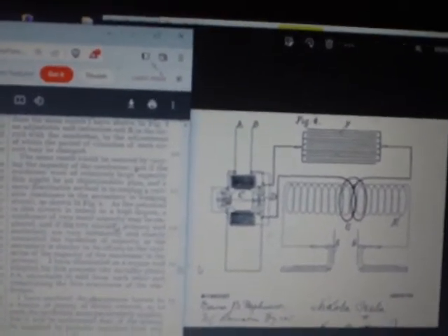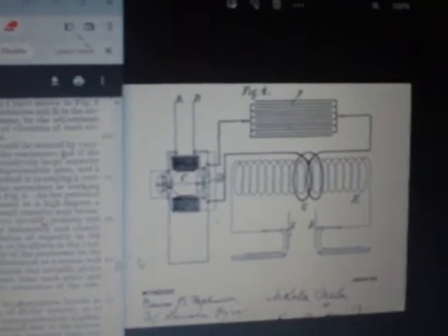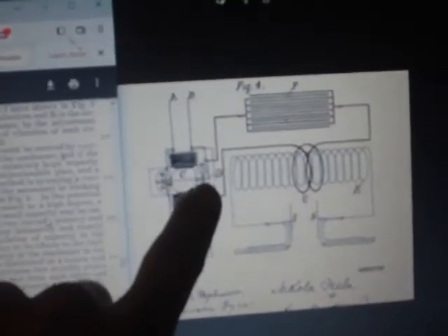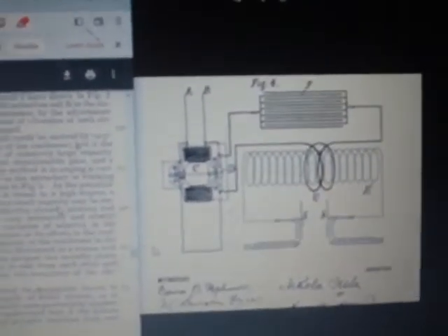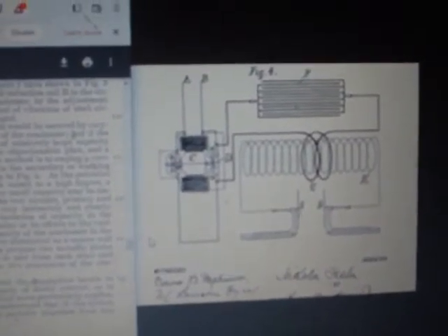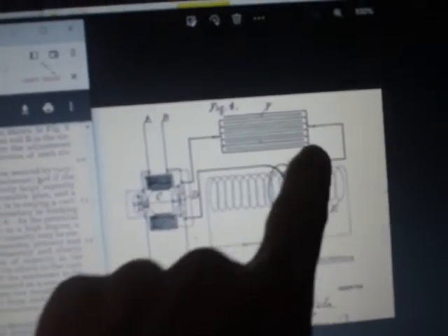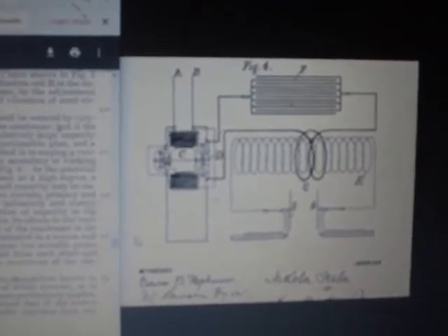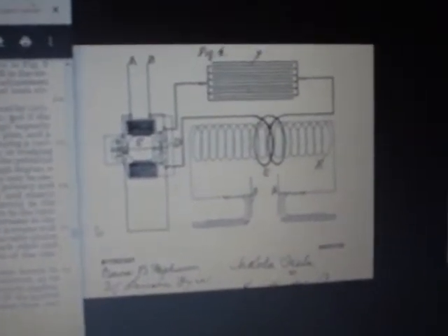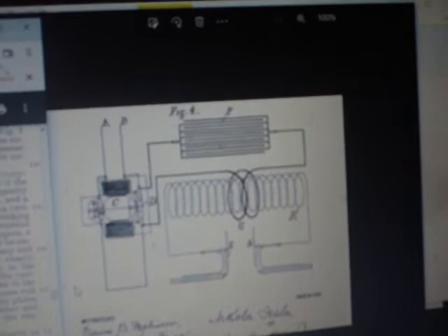By the way, it will probably be a capacitor bank, okay, because the voltage will be so high here that your capacitor will be too expensive if you buy a single capacitor of high voltage. So you can put several relatively high voltage capacitors in series to secure your circuit so that you don't blow them up. I have illustrated.